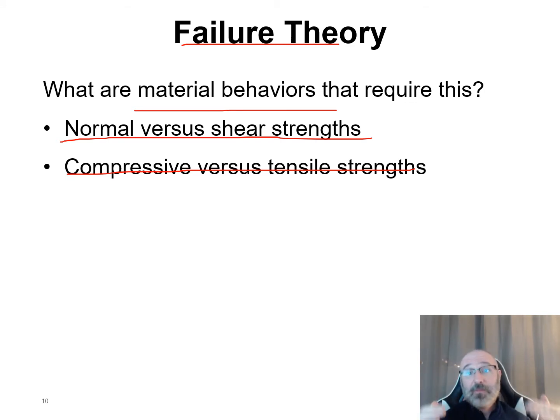Think about a bridge deck, the way it's loading in 3-point bending. Sometimes it's in compression, sometimes it's in tension. Go back to even some of our previous courses where we talked about that with 3-point bending. If you look at a beam in 3-point bending, if it's going down like this in the center, all of a sudden the bottom of that beam is going to be in tension and the top of that is going to be in compression. The same applies for a bridge deck, where you're going to have certain portions of it in compression, certain portions in tension, and it could be cyclic loading as cars are driving over that, going back and forth, putting the top in compression and tension and the bottom in compression and tension as well. So that's something that is interesting to see, comparing the compression versus tension results.